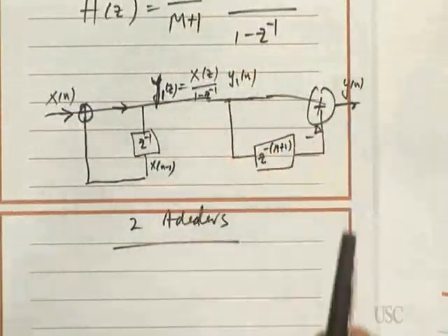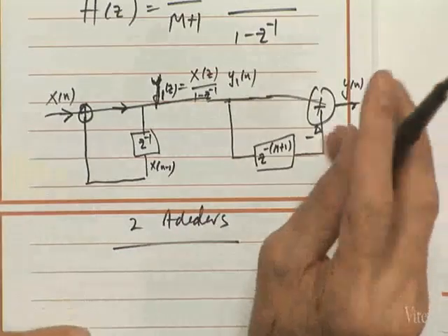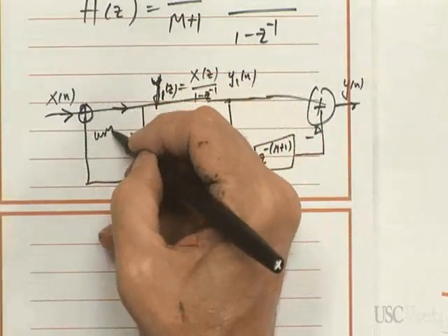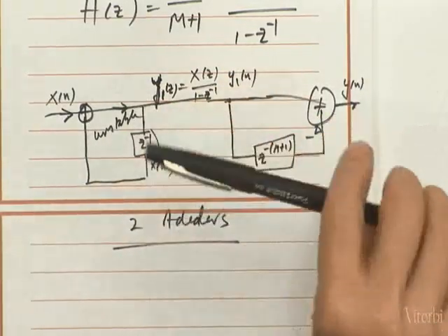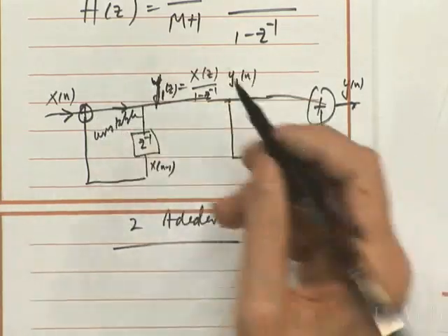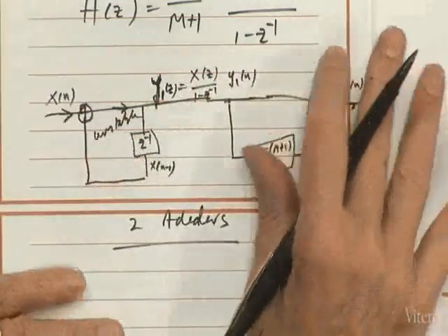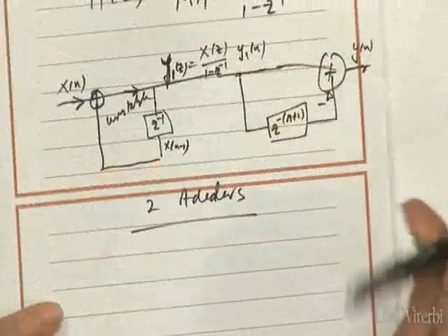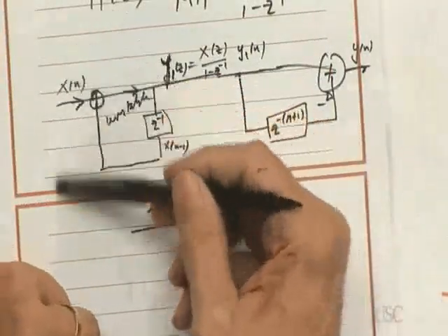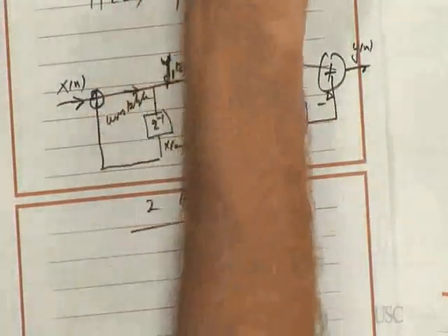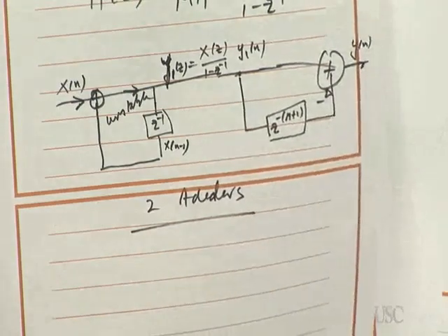Now, the only problem with this is it just violated something I just got done talking about 5 minutes ago. This filter here is unstable, right? This is an unstable filter because it just keeps adding samples over and over again. But it turns out if you implement this with what we call 2's complement arithmetic, I'll touch on this briefly toward the end of the class, at the end of the course, then you can actually implement this without introducing overflows or anything. So anyway, it's just kind of an aside as we're going along. Just some interesting little tidbit on implementation.